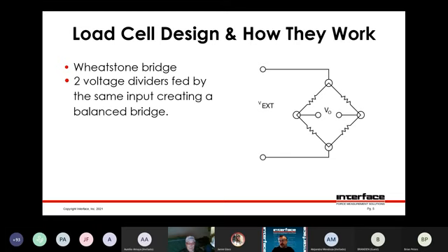And so moving on, the strain gauges are basically variable resistors. They're glued to the surface, and they stretch or compress as the surface deforms. They're wired in a Wheatstone bridge configuration. What that does is it allows you to apply a voltage across the bridge and then get a signal output from the bridge. And the signal is in millivolts per volt, so millivolts out per volt of excitation. And it's really measuring deflection in the system using strain gauges. It's quite nice, very repeatable, and it's a method that's been used for many years very successfully.